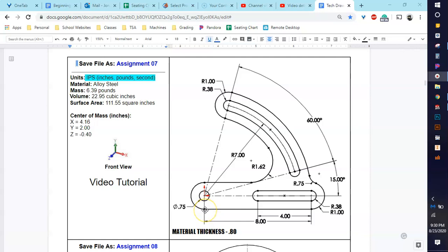It's just a known thing because that's how the shape is built. So when you trim the line that's here, it no longer makes that tangent. So you lose the tangency there, and anything over here. It also sometimes makes these horizontal lines no longer horizontal, meaning they can change on angles and such.